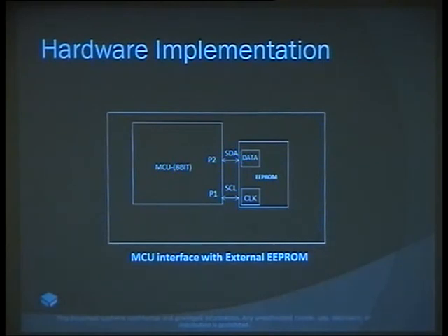So all you're doing is passing the parameters, saying, okay, set the timer register to this value, activate at this time. So you are calling on the peripherals and on the data structures through the API layer and the peripheral layer. But as we said, you're not trying to change those layers. Those layers you're trying to leave as standards.